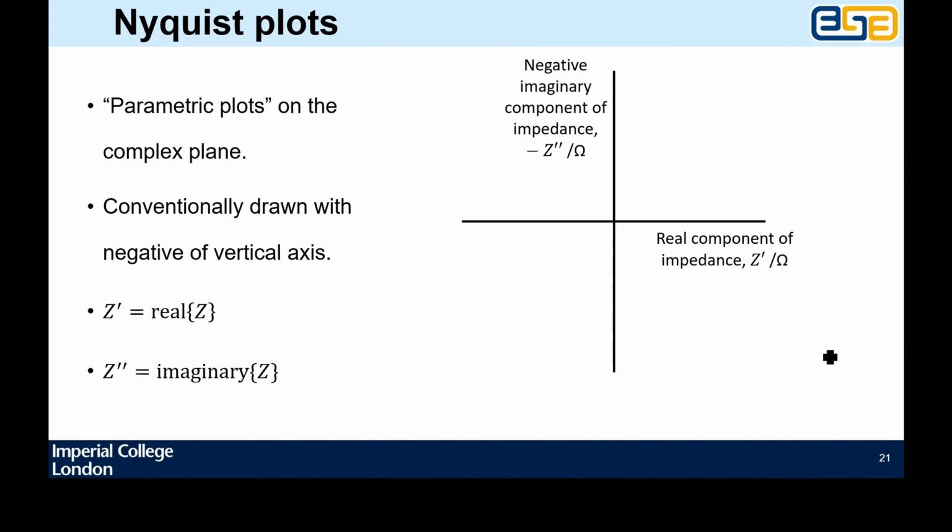And now we come to the bit that you will have seen in so many papers, which is the Nyquist representation of impedance behavior. So you have a way of graphing the impedance behavior of your system. These are parametric plots in the sense that the horizontal axis and the vertical axis are both results of the thing, and you parameterize it in terms of omega. So it's not like a classical thing where you have y versus x and you put in x and you get y. This is real and imaginary impedance contributions. You put in different omegas and you get different coordinates in that space. Okay?